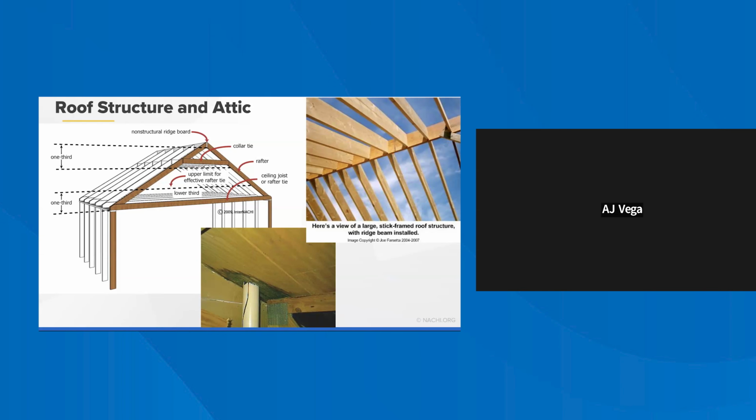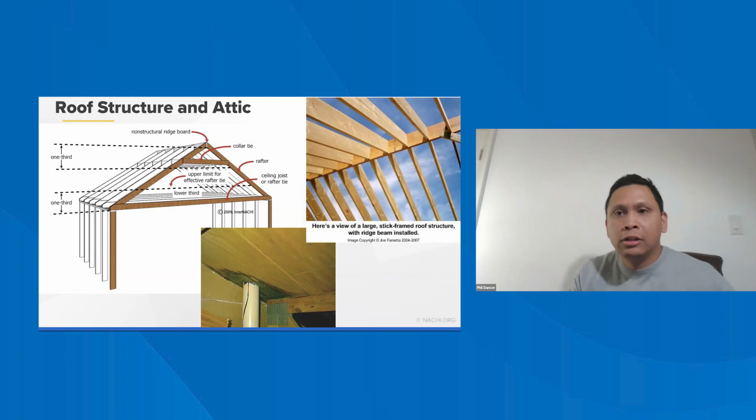Can you talk a little bit on seasonal truss uplift on interior non-load bearing walls? So for those of you that aren't familiar with truss uplift, that's a really good question, by the way. Truss uplift is where you've got the trusses actually lifting upwards due to the different temperatures that are in the attic itself.